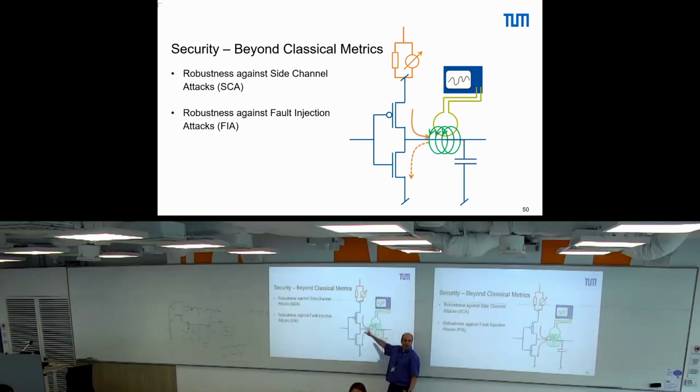But at the end, it boils down to you have a switching activity and you can observe what is computed on chip. So, in order to protect against this, there are strategies like masking, hiding, and so on. So different modifications you can make to your circuit, special kinds of implementations to get rid of this. This comes on top if you really want to go beyond what is pure digital design. So you have also to implement stuff like that.